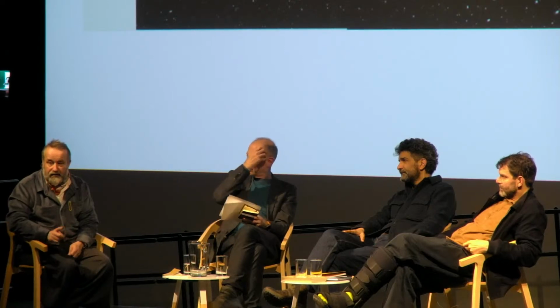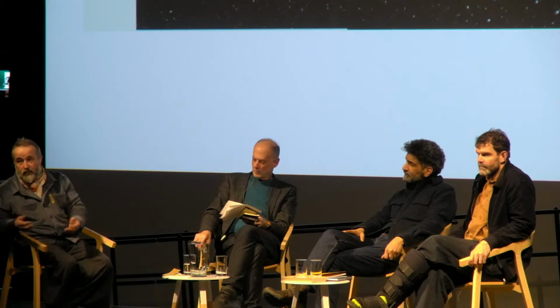Yeah. And lastly, Arup have been developing testing for the Padre Pio Church in South Italy in 2002 or 3, using an ultrasound system. So they were able to check the integrity of the material, not its capacity, but definitely to check its integrity. You would be using exactly the same system that you use in concrete testing, using ultrasound and so on. You can transpose that to stone to check the integrity. So that's been rolled out in several projects already. And I think, as Steve says, with more money, we could definitely improve the grading of stone.